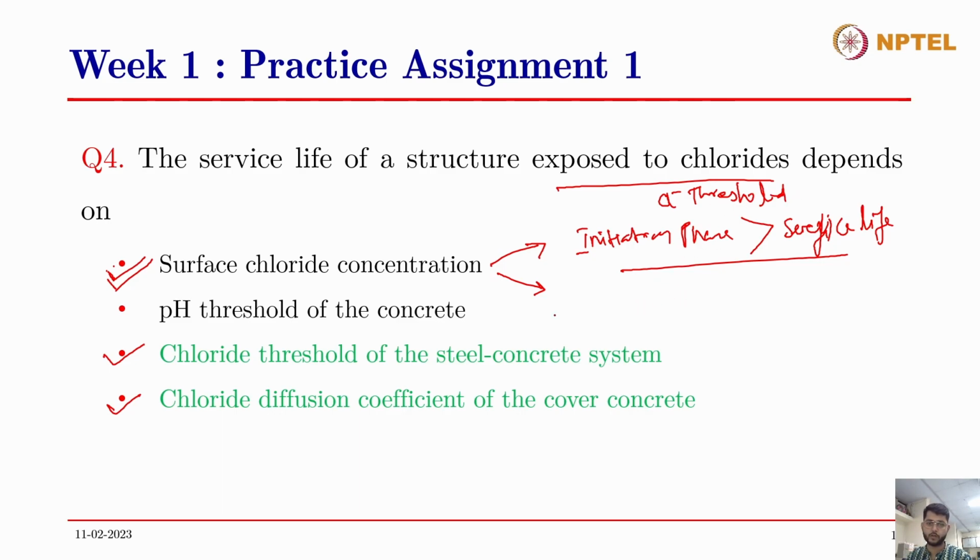Of course, chloride threshold has something to do with it. The chloride threshold will govern the service life. The chloride diffusion coefficient will also govern: let's say the surface chloride concentration is low, but if the diffusion coefficient is high, then more and more chlorides will get diffused, and ultimately the chloride threshold will be overtaken. So that will affect the service life again. Anyway, I hope that is clear what I wanted to mention.